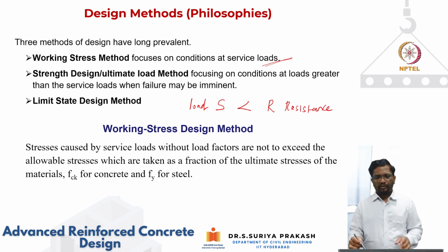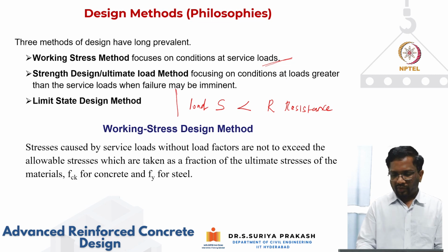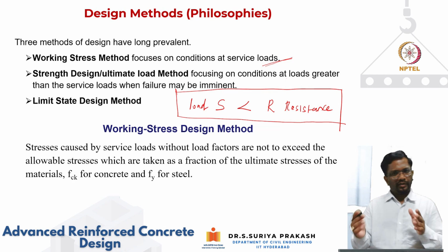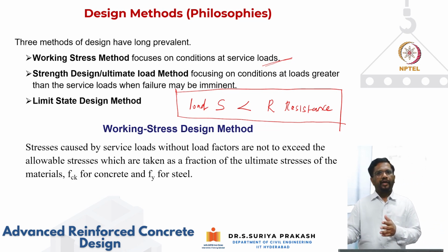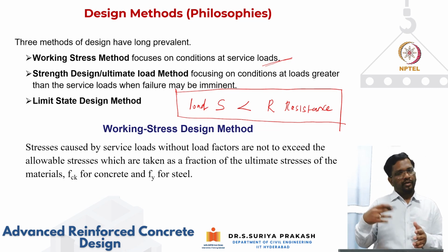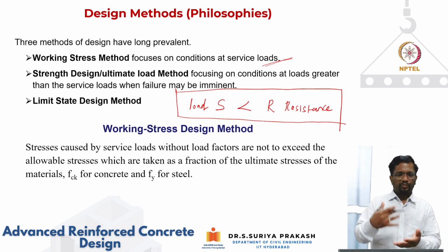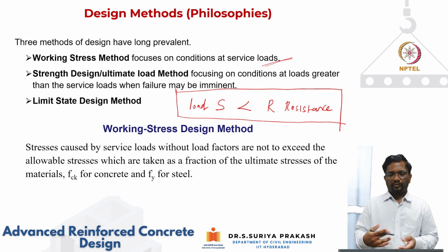So our goal is basically to make sure that the load effects are less than resistance, or in other words, the resistance has to be greater than the load effects. The load effects can be quantified in terms of internal forces: bending moment, shear force, and axial force, or combinations also.